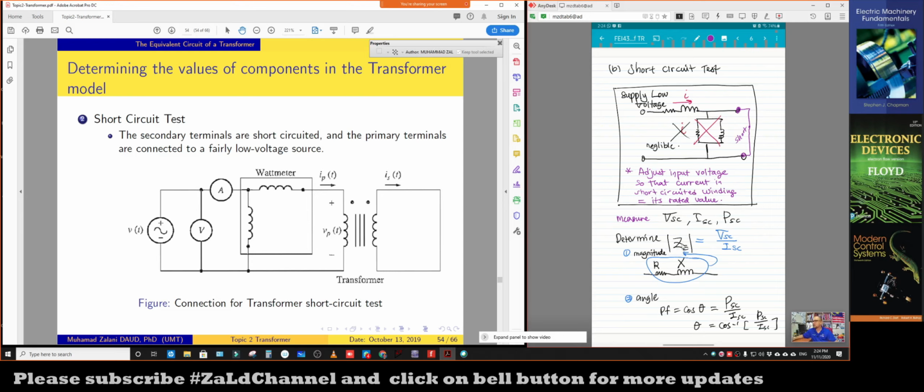ZE is the magnitude of the series elements here, series components. ZE is basically REQ plus jXEQ, right? So that is ZE. So we determine the magnitude of ZE for the series one, and then also the angle. The same thing that we have done previously in the open circuit test, where we determine admittance, which is the parallel branch.